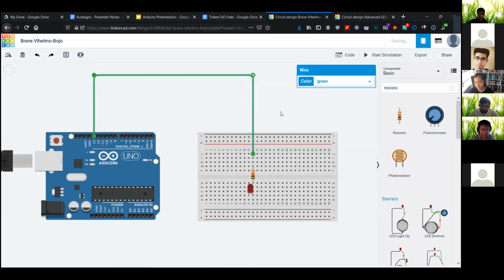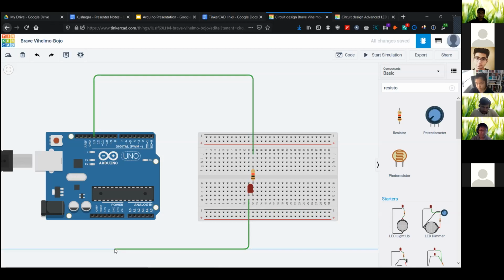Now, if you remember what we just discussed, technically the resistor and the wire are connected because these 5 holes in this column are internally connected through the breadboard. The resistor is connecting with the LED through its positive terminal, the anode, as the resistor is crossing over the gap. Now I'm going to take another wire from the negative terminal of the LED and connect it to one of the Arduino's ground pins. So I'm going with the right ground pin. You can also use the left one. And our circuit is complete.